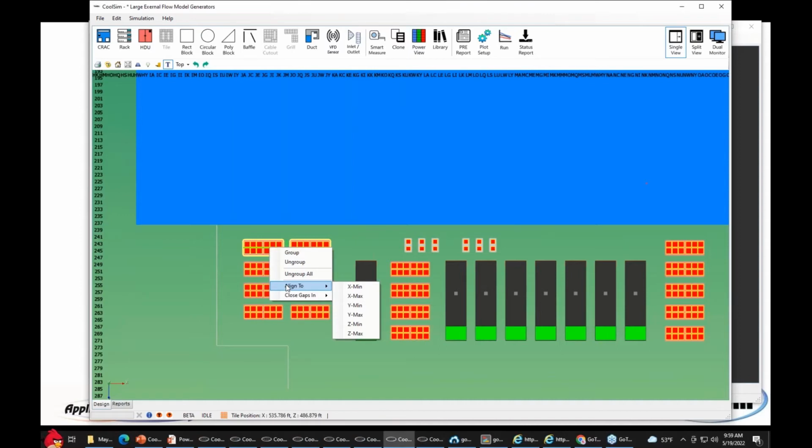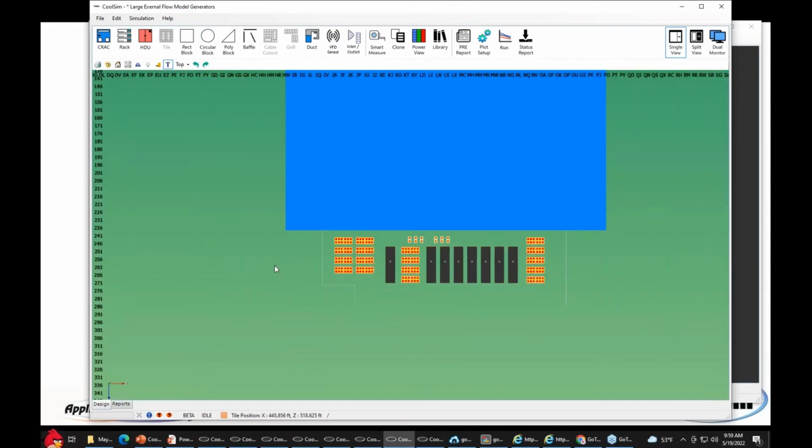It's always the case in CFD, you want good alignment so that the mesh doesn't create unnecessary cells that might have trouble converging. So we have this very nice closed gaps, aligned fronts feature, and it works on groups as well. So, yep, put those in. Now, you go ahead and set the airflow just like we did before.